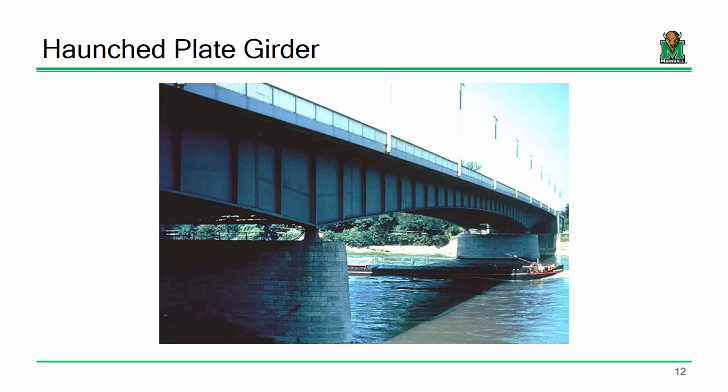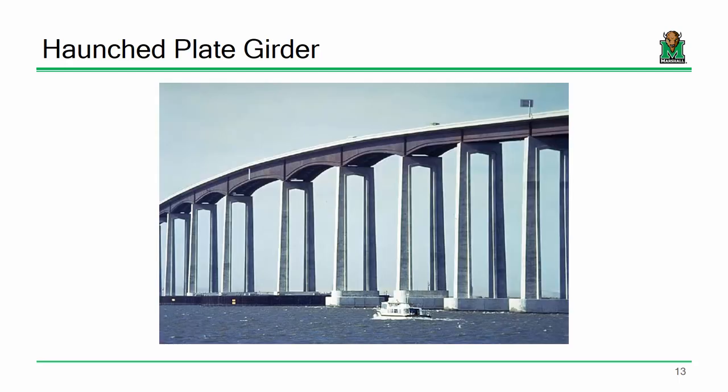Now, granted, it's a truss, and we don't think about moments when we look at trusses, but the concept is generally the same. Depth equals stiffness, and we need that deeper section where we've got those larger forces. So it's just something to consider. This is just another example. They had some significant elevations they had to meet on either end of that construction project.